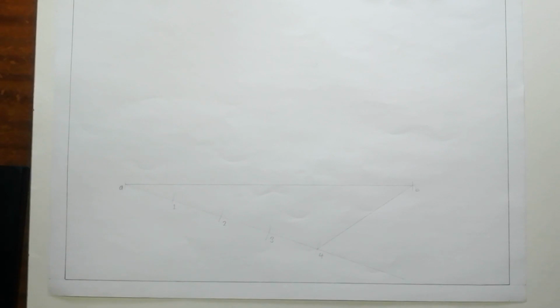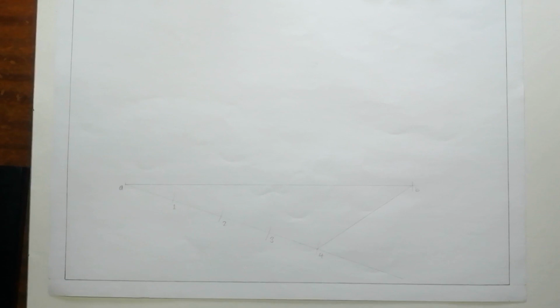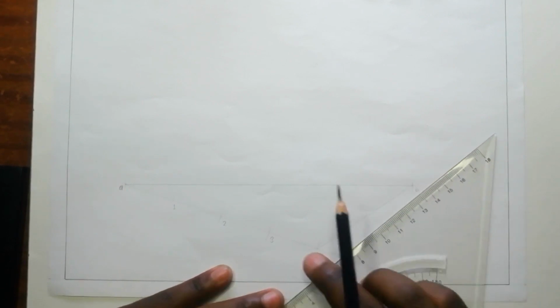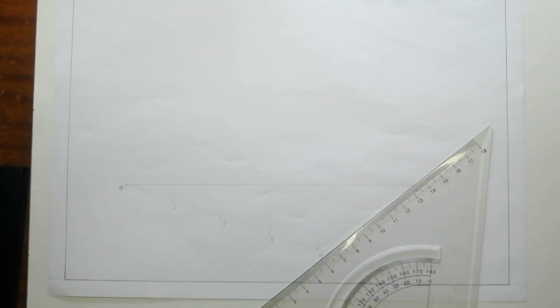And then what we need to do here is go back to our ratio. This is very, very important. We know that after we divide the line, usually we transfer this line to 3, 2, and 1, or simply we're going to draw parallel lines to 4B at points 3, 2, and 1. It's usually a procedure that you do without even much thought. But this time when we're drawing a triangle, when we've been given the ratios of the sides and the perimeter, we need to be selective which points we're going to transfer this line to.